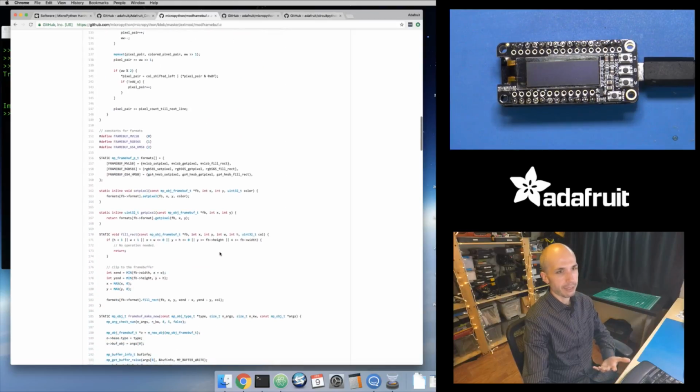It's basically a C implementation of basic pixel commands. So this takes a chunk of memory, which is your display memory. So for this SSD1306, it's like a 1-bit display. So in a byte of data, it can pack like 8 pixels worth of display data. And it takes that buffer of data and a pixel format, and then it implements your basic put pixel, get pixel, draw line, draw rectangle, fill a rectangle. It actually has text drawing and stuff built into here, although in previous videos I've shown I have a separate text library that can use external fonts and things. But all of that is in a nice C implementation, so it's really fast.